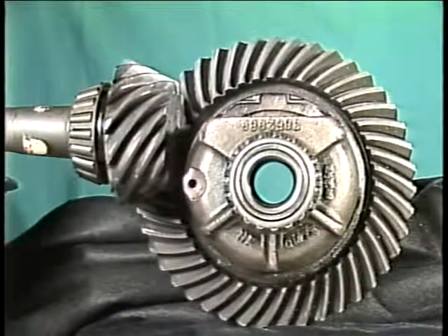The smaller number of teeth on a hypoid pinion means that larger ratios can be obtained with a hypoid gear set than with a bevel gear set of the same dimensions. The gears we've looked at are some of the most common types of gears that are used, but keep in mind there are other types of gears as well. There's also a variety of gear set arrangements that are commonly used. When we return, we'll take a look at some of the different types of gear sets and see how they operate.